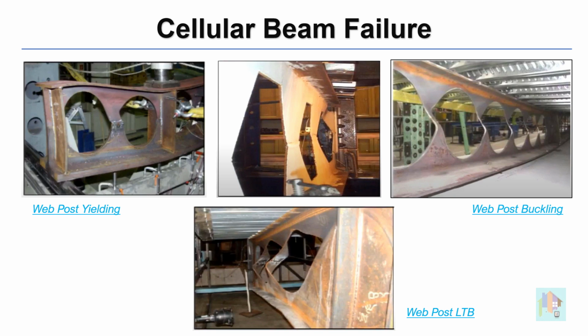Note that these sections are not good for axial force or high shear as we are deliberately weakening the web. Not only that, due to cutting and welding, there is more residual stress than in the normal wide flange section. We need to perform several additional checks, including checks for shear and tear of the welding for the safety of the member.